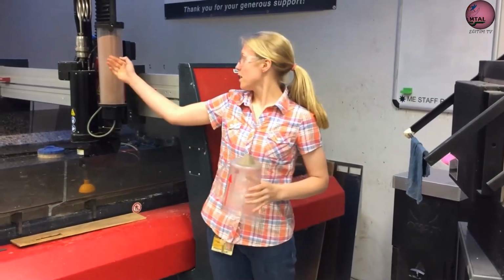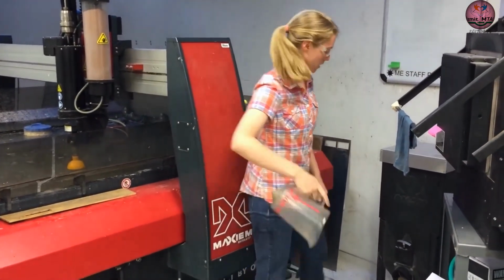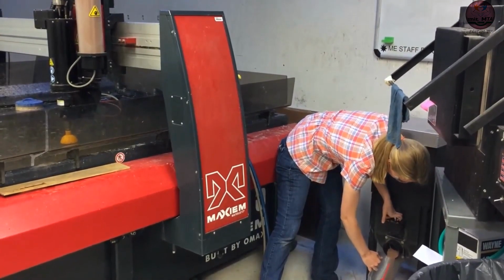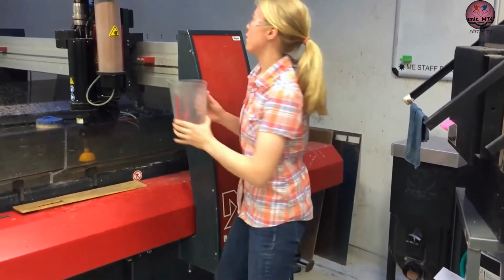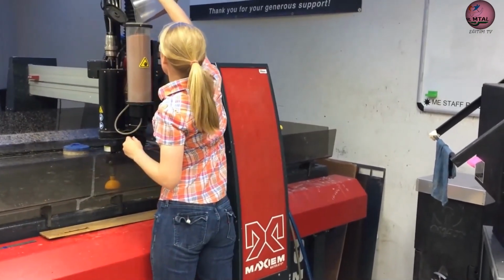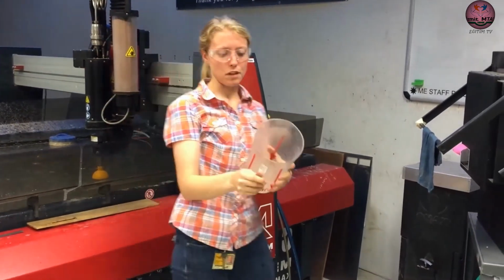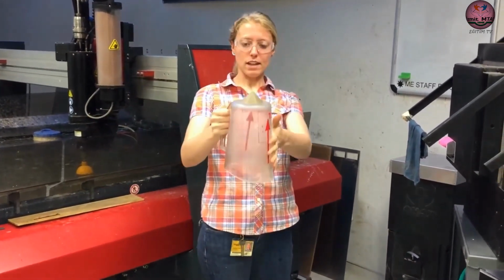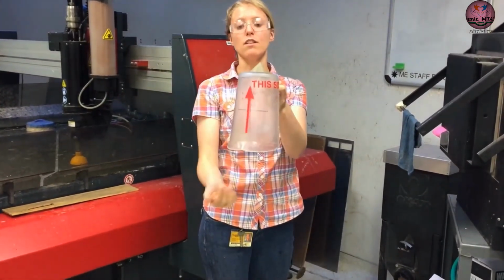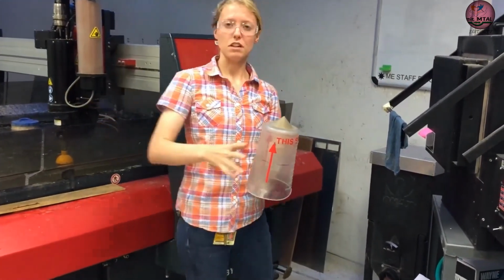Check that the garnet hopper is not low before you start your job. Use this pitcher and put garnet into it. Flip up the top of the hopper and pour it in. Make sure when you're finished putting garnet into the hopper, always keep this pitcher with this side up. If water gets into the pitcher, it can cause the garnet to clump together and clog in the machine.